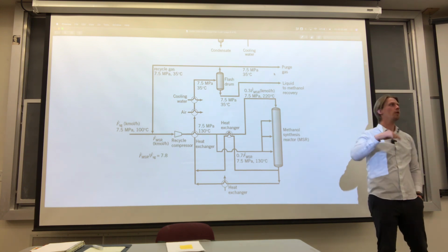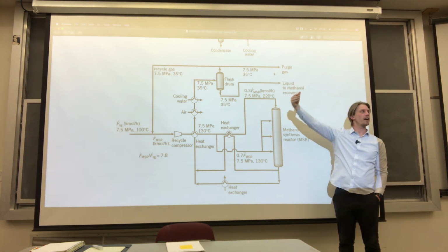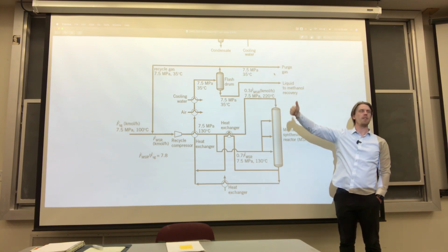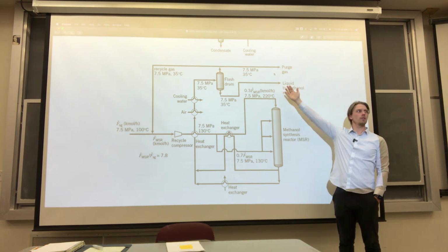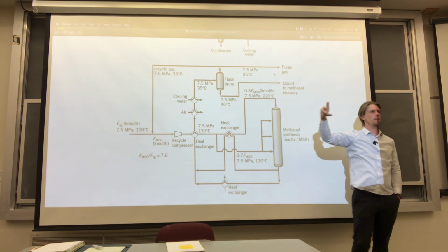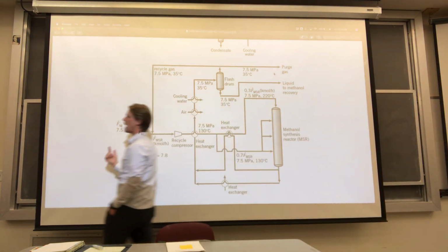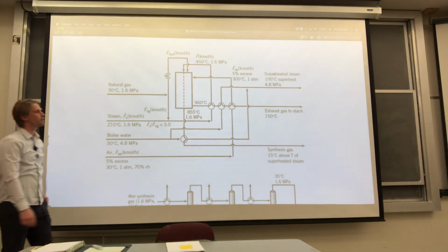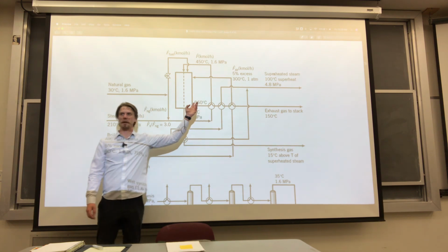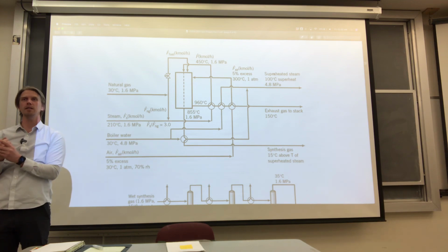So you'll need to figure out what your theoretical required oxygen is to burn this purge gas, add in the 5%, add in the humidity, because that's what you're actually going to be burning it in. Then those air streams are going to be entering the reactor at 300. Your purge gas is going to be entering at 35 degrees C. Then you'll be determining the outlet composition based on the steam reforming reactor's outlet condition, which is the 960 degrees Celsius. Right? So your purge gases are going to be leaving at these same conditions, and you're going to want to figure out how much Q heat is given off.